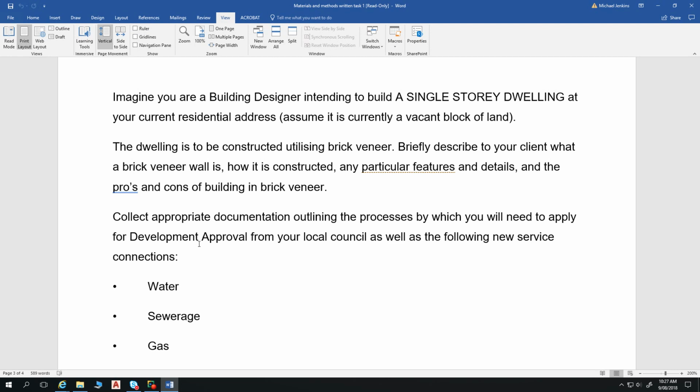Timber, when it's in a structural frame and braced correctly, and then has an external skin of brick veneer that has articulation joints in it, so joints along the wall every 6 metres or thereabouts to allow some movement, you can then have movement without structural impact or significant structural impact on the building, and without any visual impact. So without us being able to see that there has been some movement of the structure.